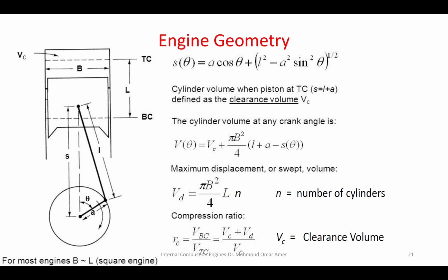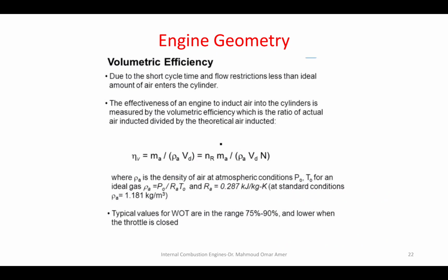And how do we know the exact volume above the piston inside the cylinder? According to the angle theta of the crankshaft. From V of theta, we calculate the volume inside the cylinder at any crank angle degree. You will only need it for research or simulation work. Other than that, you are not required to memorize it.